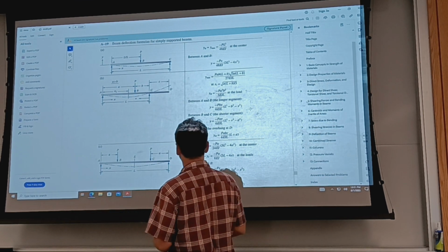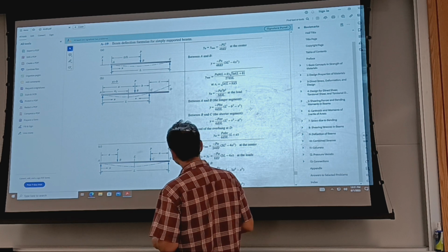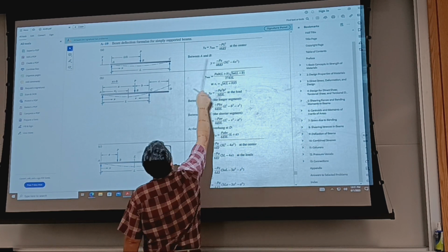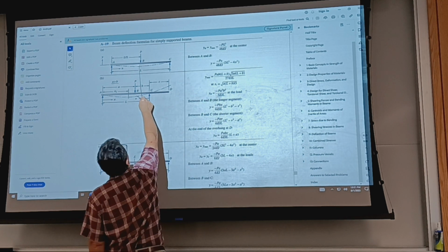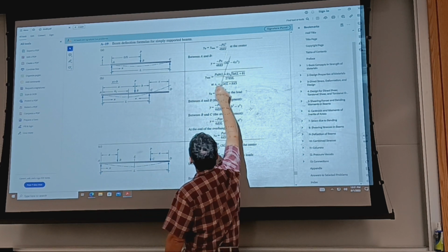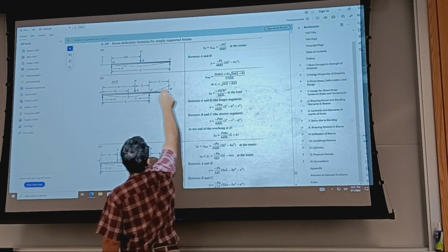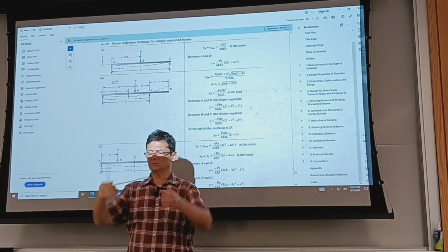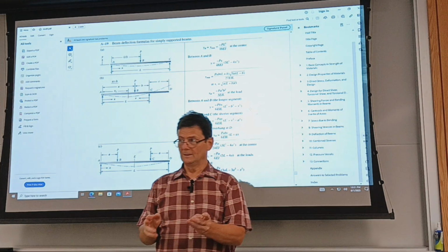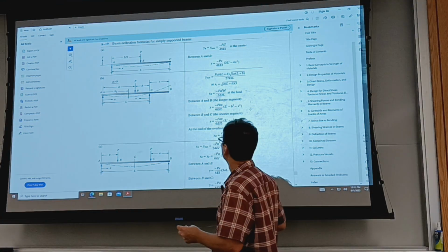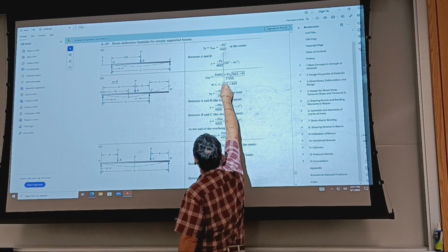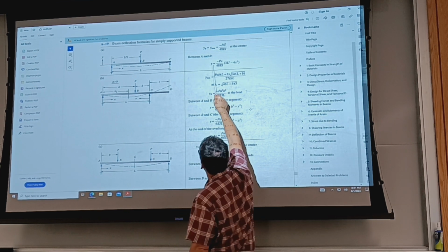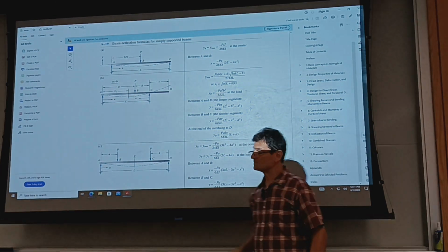Okay, and it allows us to find the maximum deflection, which is the deflection at B, and it has this magnitude. So it depends, of course, on P. The bigger the span, the more deflection. It stands to reason. Material stiffness and geometric stiffness will reduce this deflection, right?